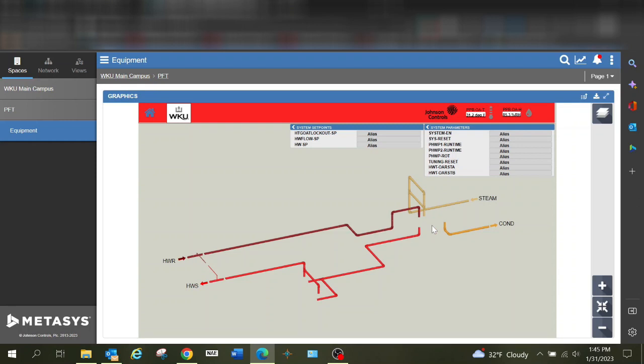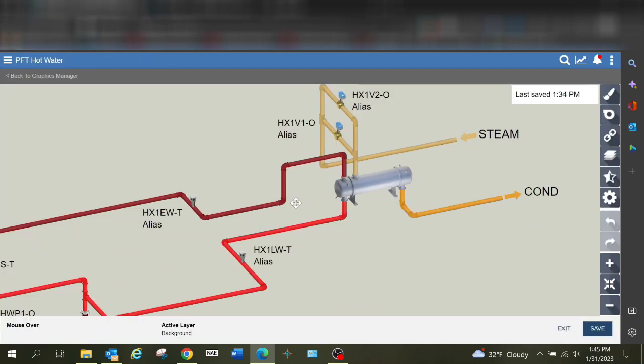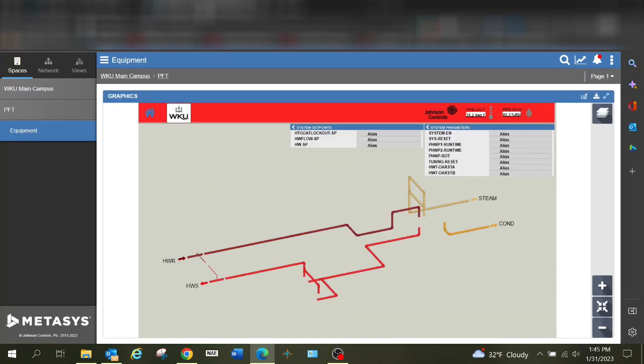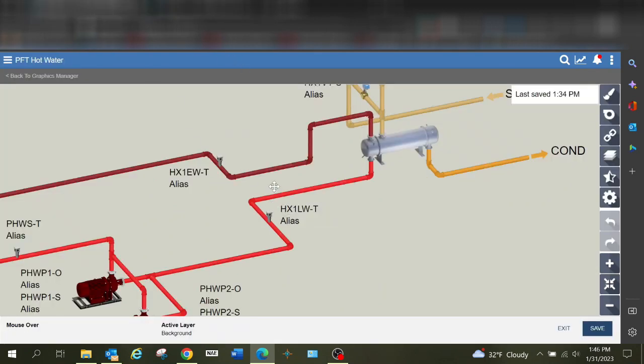Some of the naming in the way that was done with the N2 systems does not necessarily get captured with the way that the graphics try to look for things. You know, they look at the name. Basically, if you were to build this out of CCT, that CAD file will populate a lot of the objects within this graphic. Unfortunately, since this is an old N2 DX9100 with the naming and everything a little bit different, it does not do that for us automatically. But we can still get this resolved. It's still something that we can work with.